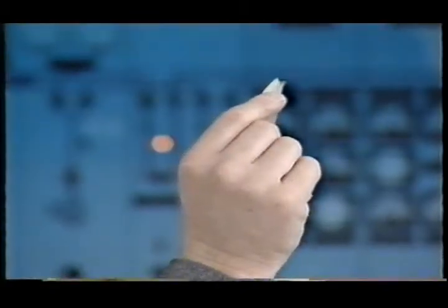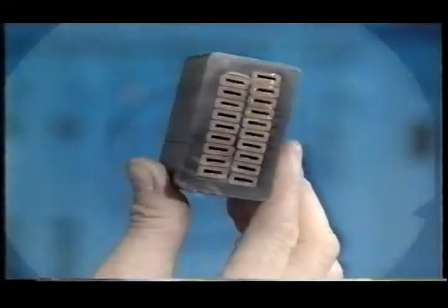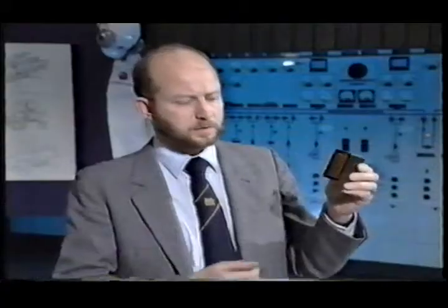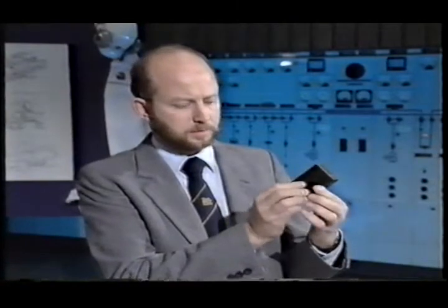For instance, the gas passages in the generator rotor winding are of a size which can be blocked by something like this being blown into it. In fact, there are some areas of the generator that can be put at risk even by an item smaller than a grain of rice. And the conductor bar itself is actually made up of subconductors with small holes in like these. So you can see how easy it is for a very small object to block the subconductors. And if several of them get blocked, the bar can overheat. If the conductor bar fails, it can cause a very expensive outage.